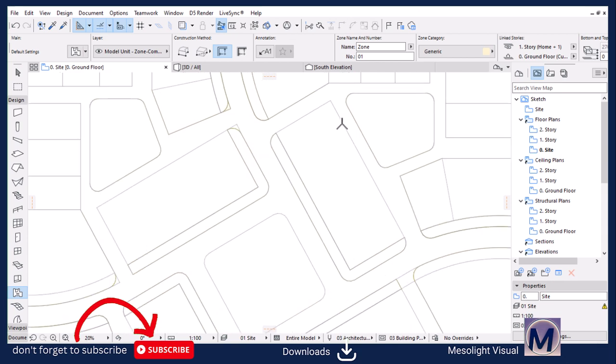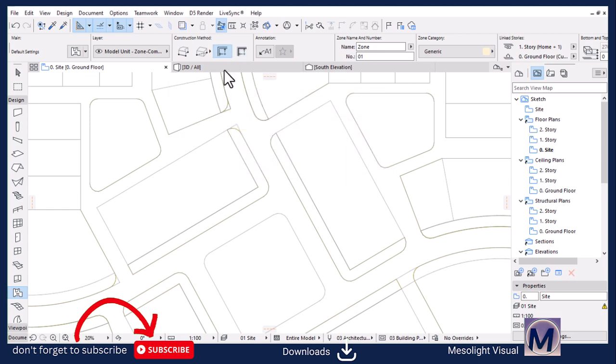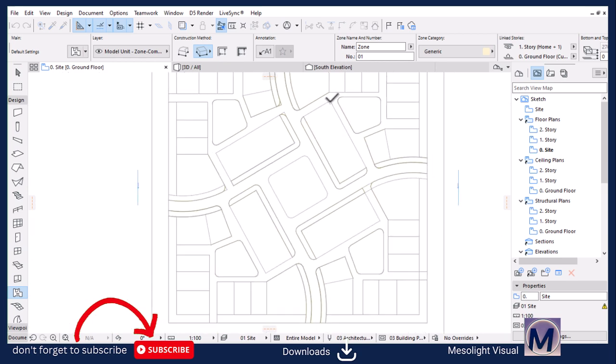And then I'm going to apply it to the site. You can try to do that, but it doesn't recognize the region. Even if you change the construction method and then you press it, it doesn't recognize. So the best way is to use this rotated rectangle, and then I can draw just like that.